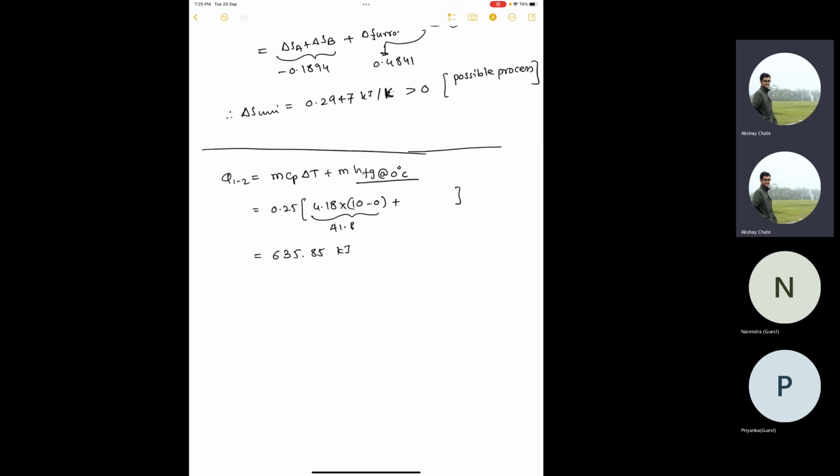It should not be then. I think it is for water, the latent heat of fusion, sir. It is the latent heat of fusion, and its standard value is 333.6. Acha. I think this 2501 is for water to vapor, because I remember when you boil 1 kg of water, you have to give some 2500 kilojoule of heat.